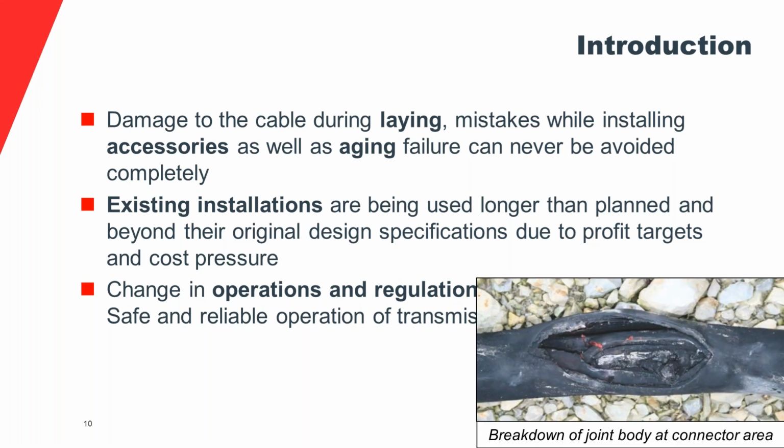And at the end of the day, this is what we're talking about. If you have a cable failure from one of these longer faults that take a longer time to actually show themselves, then this is one of the results. You can see the splice body near the connector, and you had a breakdown there that was due to a fault that, for instance, would have passed the VLF test, because it takes so much time to actually show itself that a 1-hour test is not going to show it. Actually, no initial withstand test would show it, and then over time, it would come to this fault.